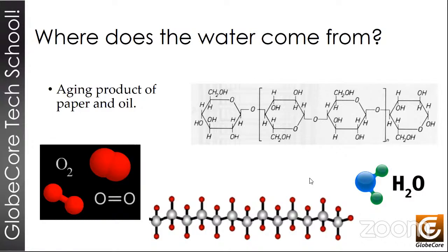has a very high affinity for water, and it will absorb water very eagerly. The greatest amount of moisture in a transformer is always in the paper, and this water causes decomposition of the paper's fibers and causes irreversible damage that can lead to electrical discharges in the transformer.